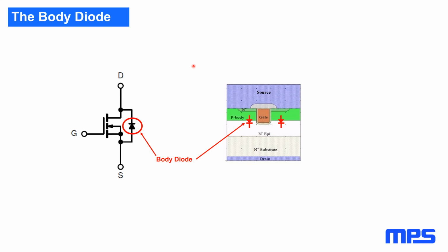When using MOSFETs in parallel to increase current capability, what can we do to prevent one MOSFET with better VGS threshold from taking all the current at startup, for instance? You could degenerate it a little bit with series resistance, but typically you don't do anything, because the one that turns on first is going to take a lot of current and it's going to heat up. And as it heats up, its resistance goes up. So they inherently share current. Usually you don't have to do anything.